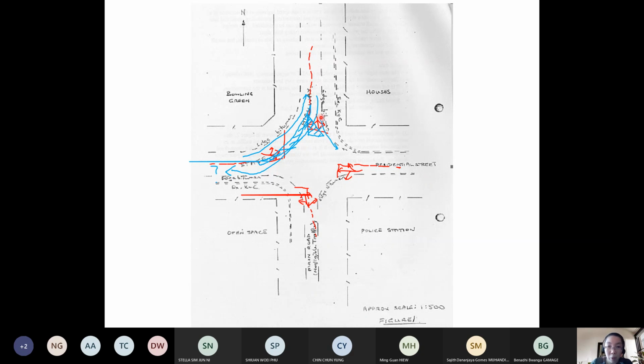that approach the roundabout will have an equal chance. As long as there is no circulating movement, the minor movement will be able to enter into the roundabout and move on. Okay, so regardless, for this one, they come at 100 km/h, they will have to slow down, move into the circulating lane of the roundabout, and then move out of the roundabout.